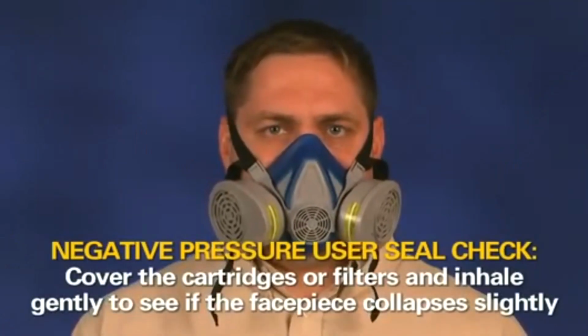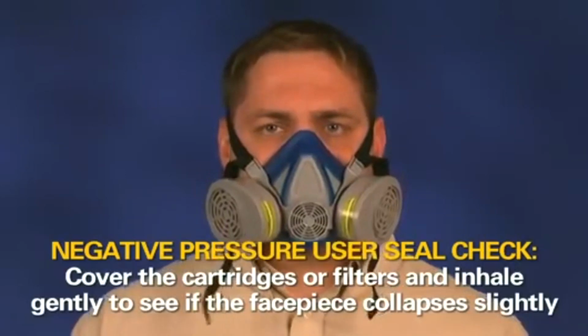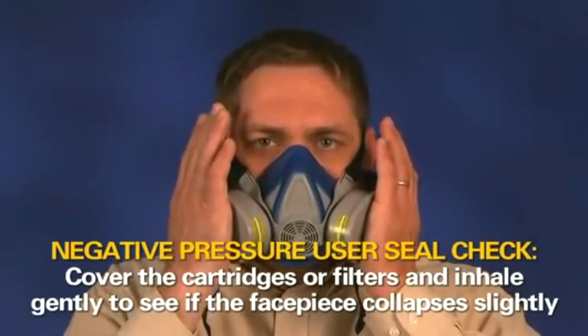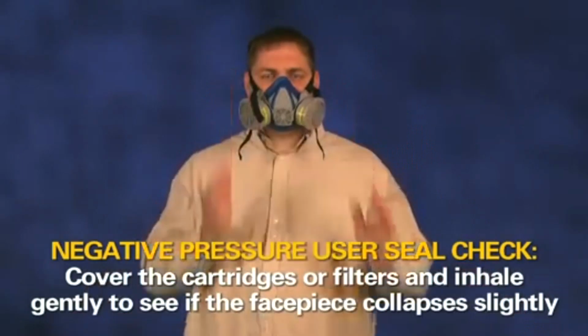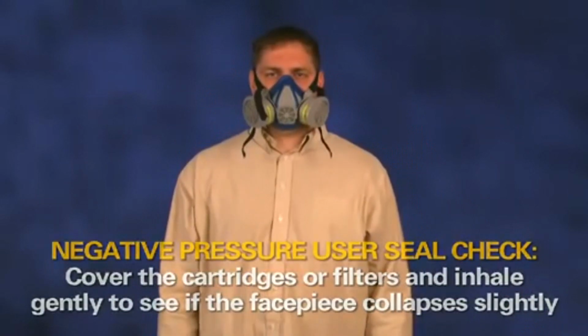Next, perform the negative pressure seal check. Cover the respirator cartridges or filters with the palms of your hands. Inhale gently. If you feel the facepiece collapse slightly and pull closer to your face with no leaks between the face and facepiece, a proper seal has been made.